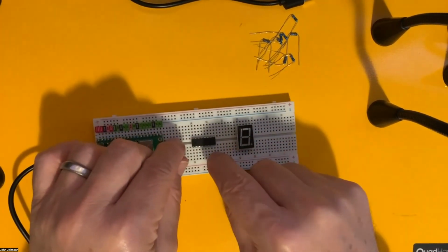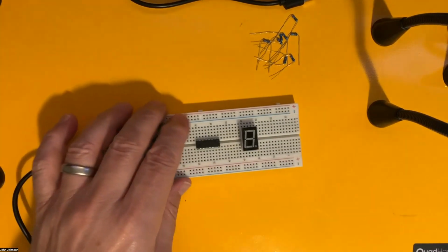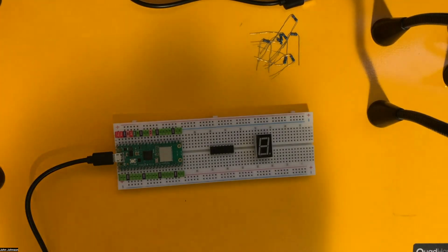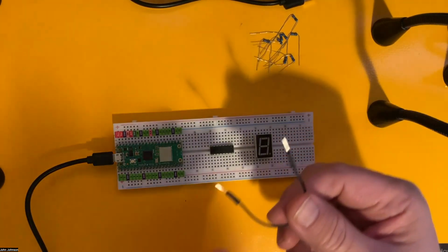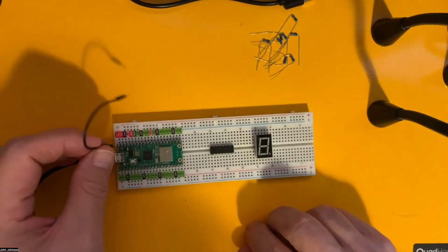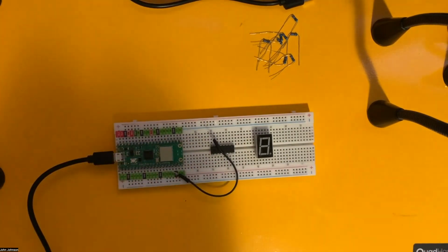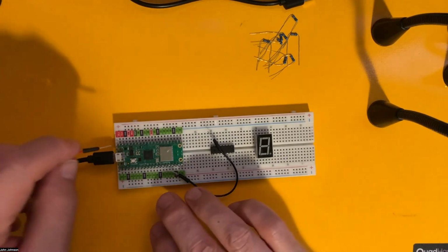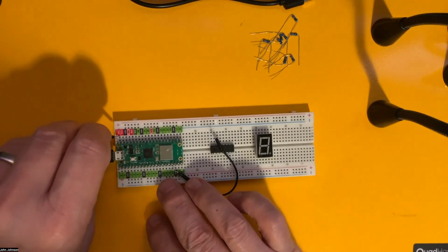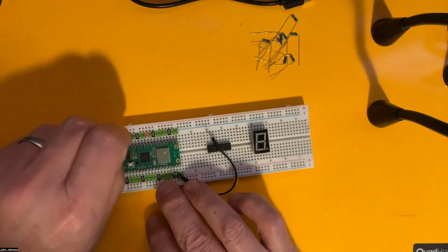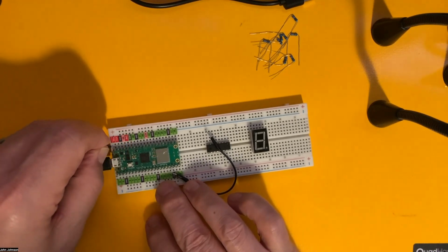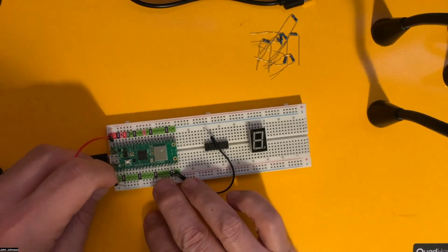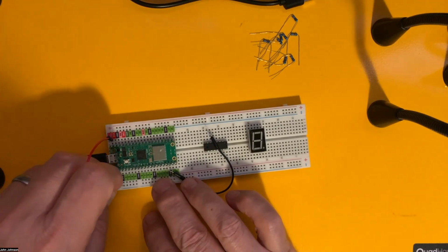Now the first thing I want to start doing is wiring up our ground and power and everything else. As I was mentioning before, we're going to try to stay as color coded as we can here. The first thing we're going to do is take our power and run it over here from the V bus. Let's go ahead and stab it in over here. This is giving me some trouble, but we get that. We're going to run that into our outer rail down here, so we're sending the power down below.